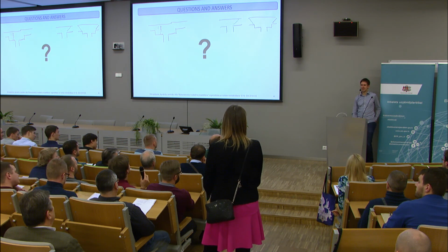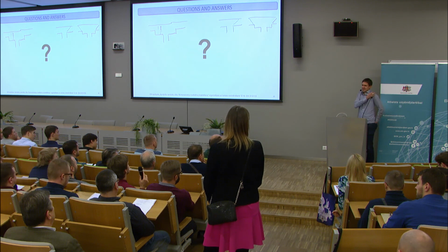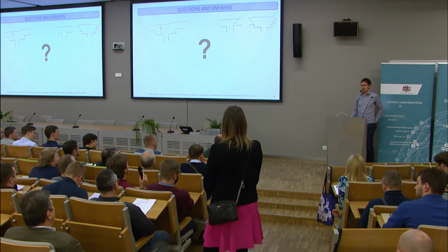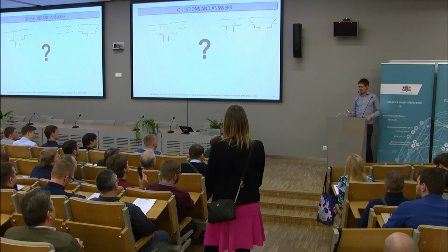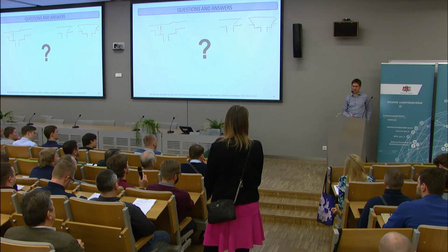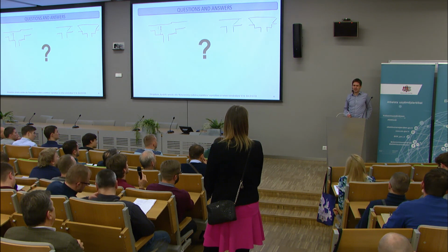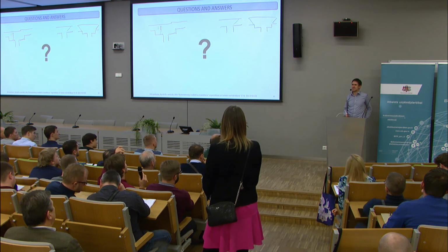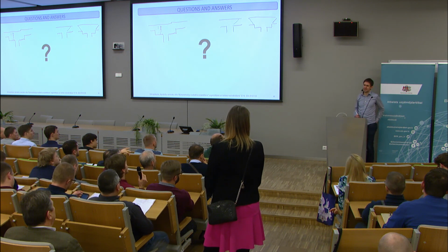Yeah. Well, as you said, if you exceed the k max, the maximum punching capacity, then the capitals do help. Do help. Yeah. So then it's possible in model code. It's possible to use capitals, but it's the last resort. You should first try to solve it with shear reinforcement, and if this doesn't work, you should, in addition to shear reinforcement, have capitals.